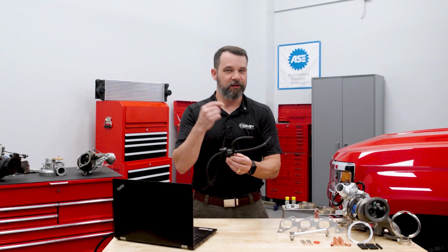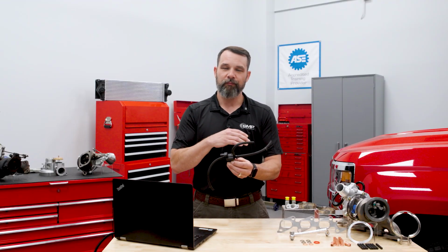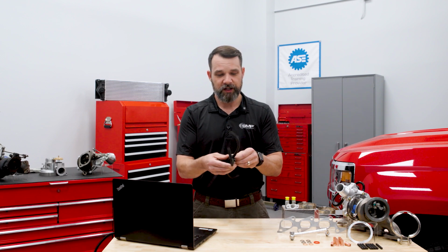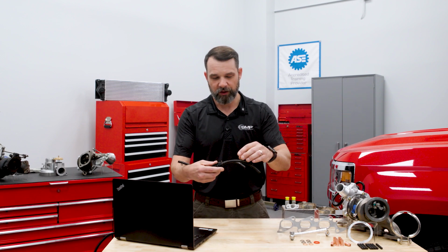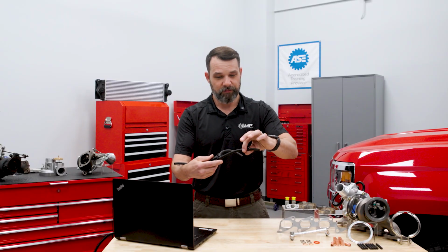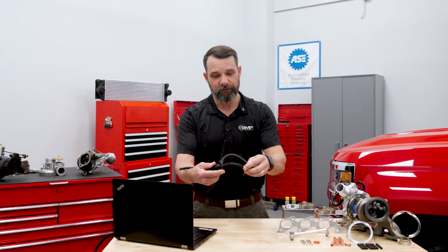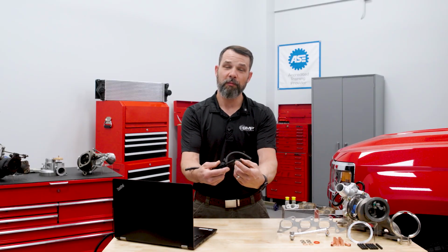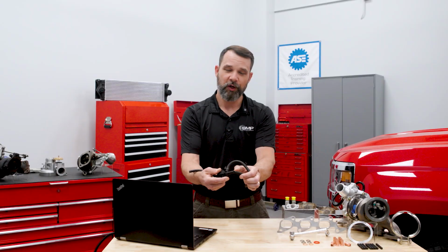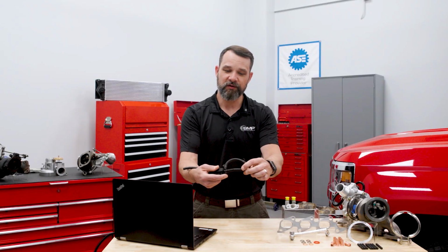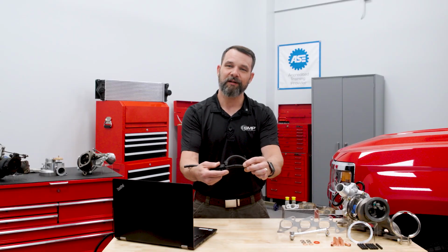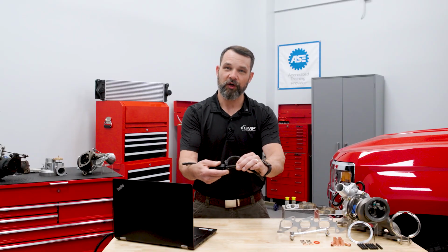But what we found in the visual inspection cleared up basically the rest of the diagnosis on the boost issue with this one. And it's going to be a little bit hard to see on there, but we had to mess with the hoses a little bit and start looking around. Something jumped up off the road apparently and hit our hose, splitting it almost in half. We've still got a little bit of hose left on this side, but essentially our boost could not work properly because there was a complete lack of sealing on this hose.